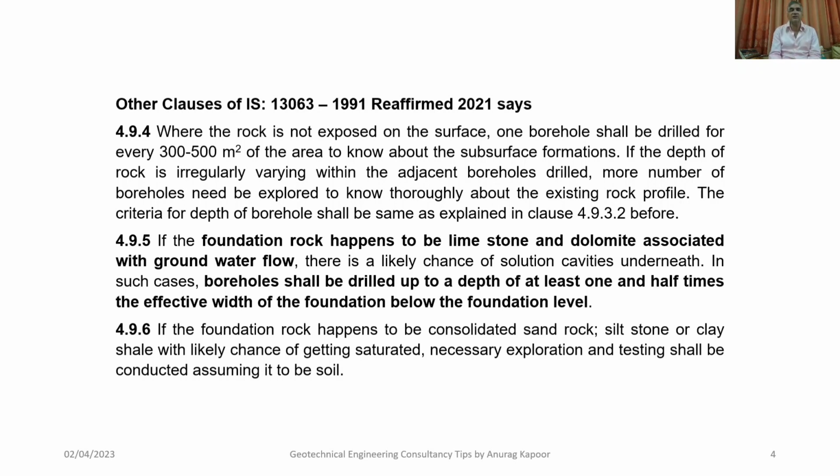Now another clause: if the foundation rock happens to be limestone and dolomite associated with groundwater flow, there is a likely chance of solution cavities underneath. In such cases, boreholes shall be drilled up to a depth of at least 1.5 times the effective width of the foundation below the proposed foundation level.